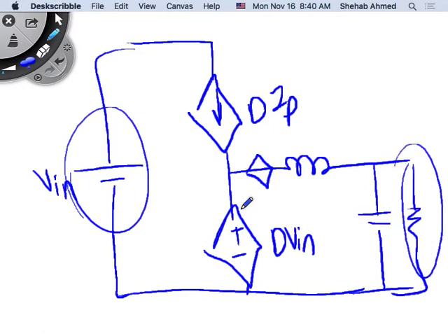So to represent losses, what we did before was include the resistance of, for example, the inductor, right? I can include that here as something that opposes. So this is my input voltage, something that opposes. It's a voltage drop. If I put a voltage drop here, I have loss. It's as if I put the inductor resistor here, right? Current is flowing in this direction, I have a drop this way, right? If I have a diode here, it has a forward drop. If I include the ESR of a capacitor, I can include that, right? I can always include drops in there as well.